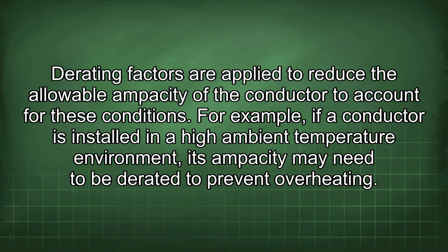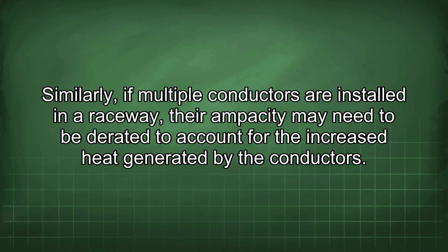For example, if a conductor is installed in a high ambient temperature environment, its ampacity may need to be derated to prevent overheating. Similarly, if multiple conductors are installed in a raceway, their ampacity may need to be derated to account for the increased heat generated by the conductors.